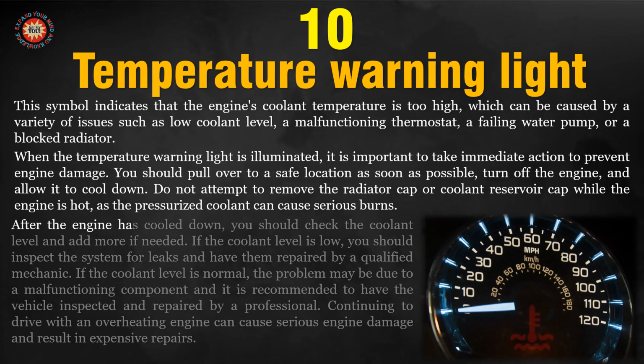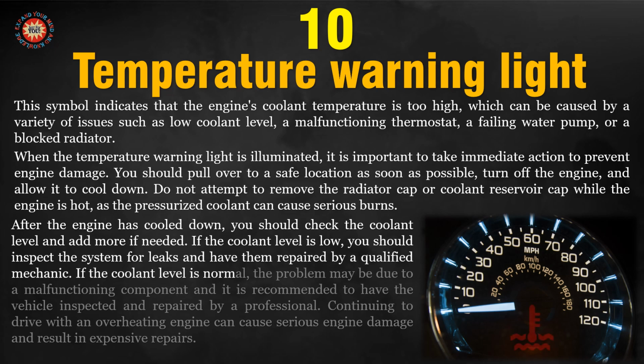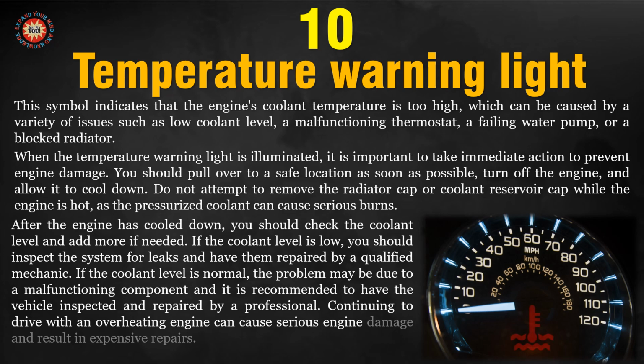After the engine has cooled down, you should check the coolant level and add more if needed. If the coolant level is low, you should inspect the system for leaks and have them repaired by a qualified mechanic. If the coolant level is normal, the problem may be due to a malfunctioning component and it is recommended to have the vehicle inspected and repaired by a professional. Continuing to drive with an overheating engine can cause serious engine damage and result in expensive repairs.